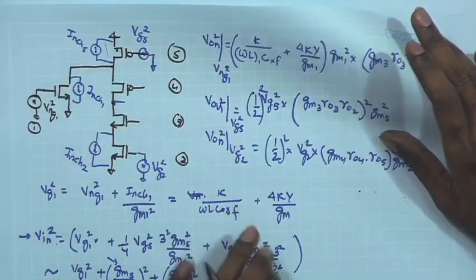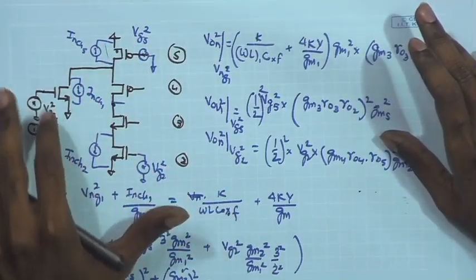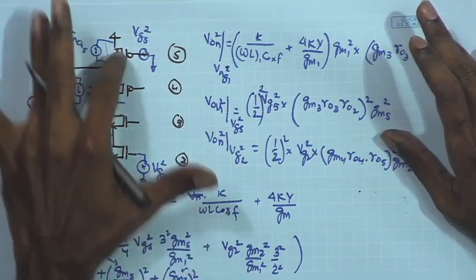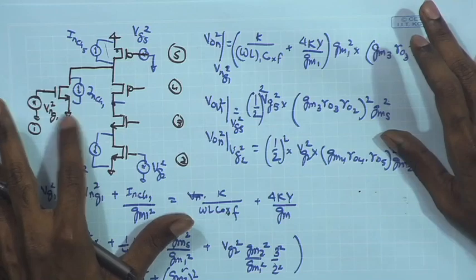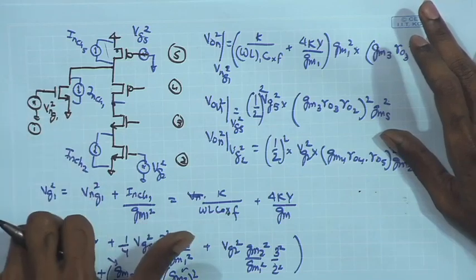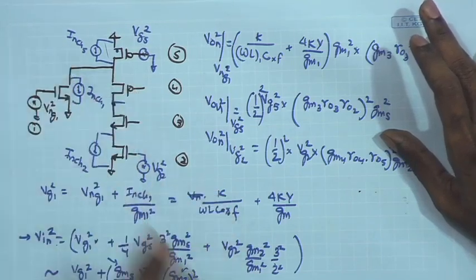Welcome back. Let us resume our discussion on the noise analysis and try to make certain other conclusions out of it regarding the sizing of the devices and the conflict with other design optimizations related to the bandwidth and the gain. So we look at the noise contribution of the three devices, the M1, M2, and M5. We have, of course, not looked into the noise contribution of the tail current source, and we have not looked into the noise contribution of these two.